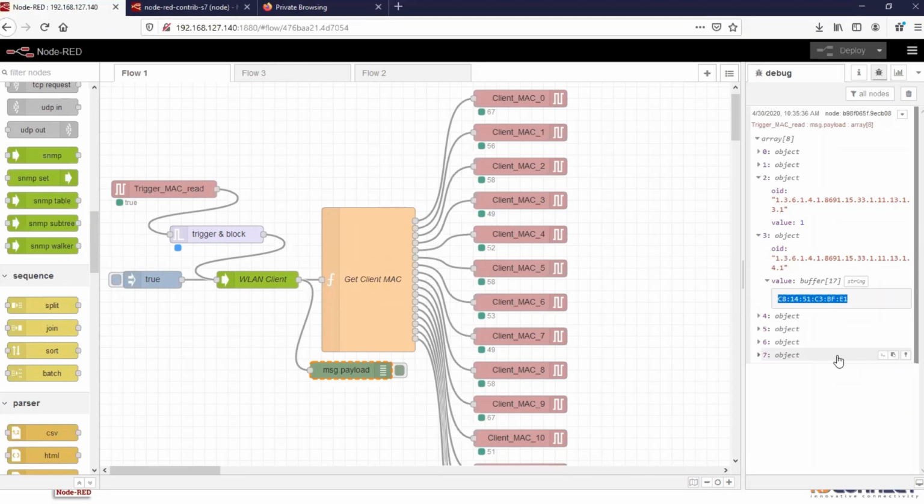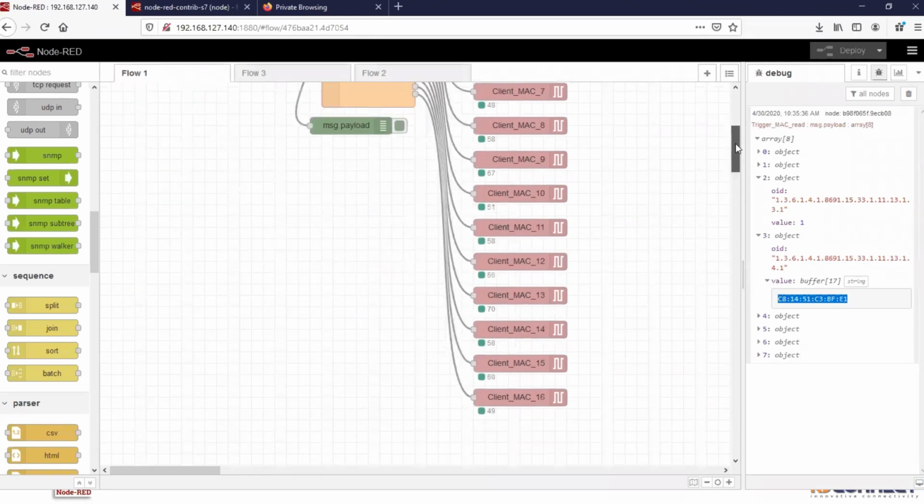We have done work for customers, for example where a customer needed to take a Modbus TCP or Modbus RTU flow meter and publish it to the cloud, but you don't want to publish it continuously. Only want to publish the average to the cloud, and we're able to take that information and do an average block and only publish the average flow for the customer for his application. So NodeRED is very, very flexible when it comes to creating different engineering examples. It's a great piece of software.